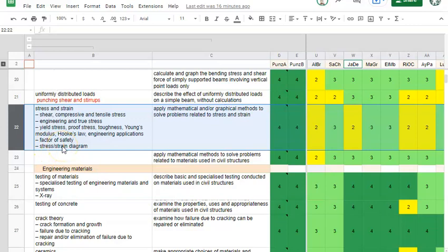So the short version is, factor of safety is if I have a ladder and I design the ladder to hold a weight or a person of 200 kilograms or 2,000 newtons, I put a sticker on there instead that says supports only 100 kilograms. Why? Because I want to give a factor of safety of 2. And that's very common in engineering.